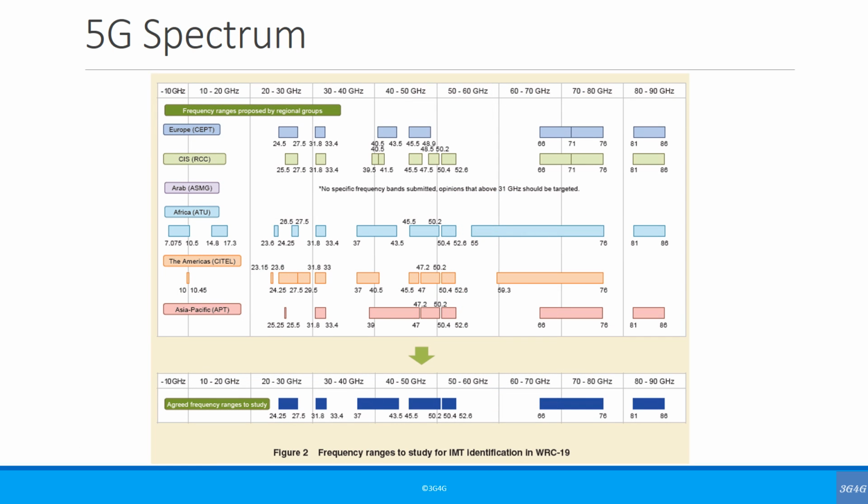For 5G, because we are running out of spectrum in the lower frequency bands, there has been a lot of discussion on what kind of frequency we should use, because you want very large bandwidth to be able to deliver really high data rates and some of these innovative services for which 5G is being touted. To have this really high bandwidth, you have to go to higher frequencies, and generally frequencies above 30 gigahertz are known as millimeter wave, because the wavelength goes in millimeters.